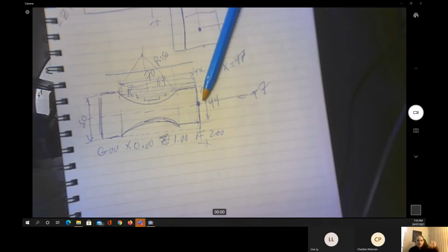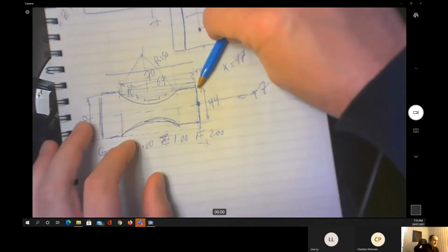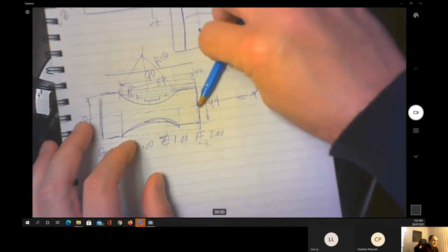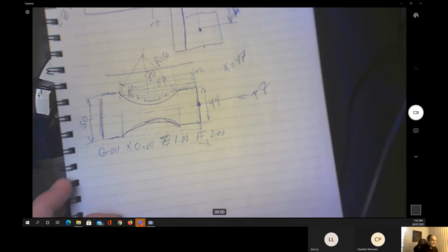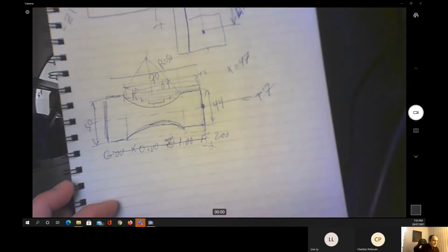When you clean the face, end to the middle. Yep, it's end to the middle. Because in that case, we are going to have the minimum contact between the cutting tool and the work part, as you can see here, just going downward until we clean the things. That's why on most turned parts you can feel a notch in the middle, because we're going from the end to the middle and doing the cut. So this line is wrong.